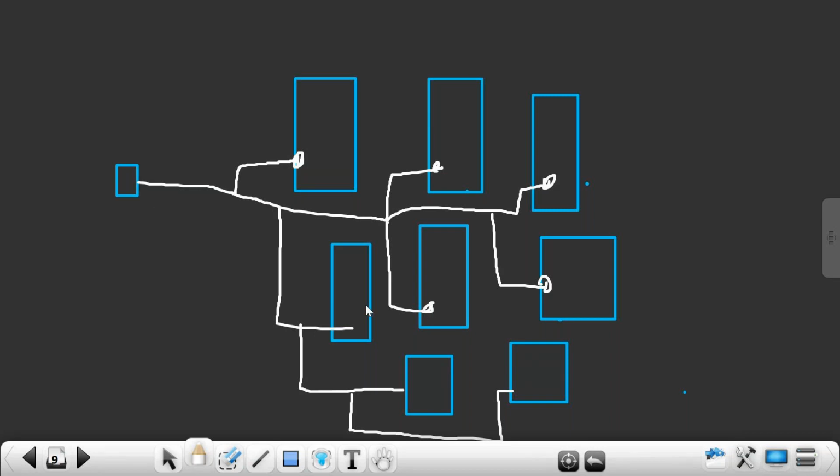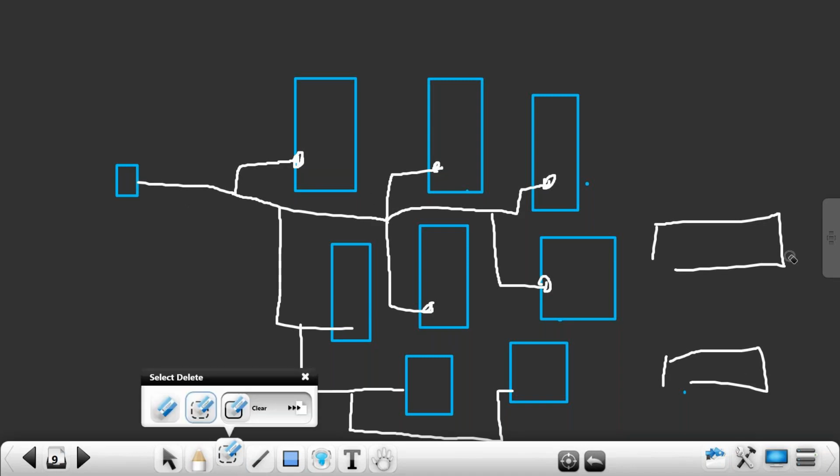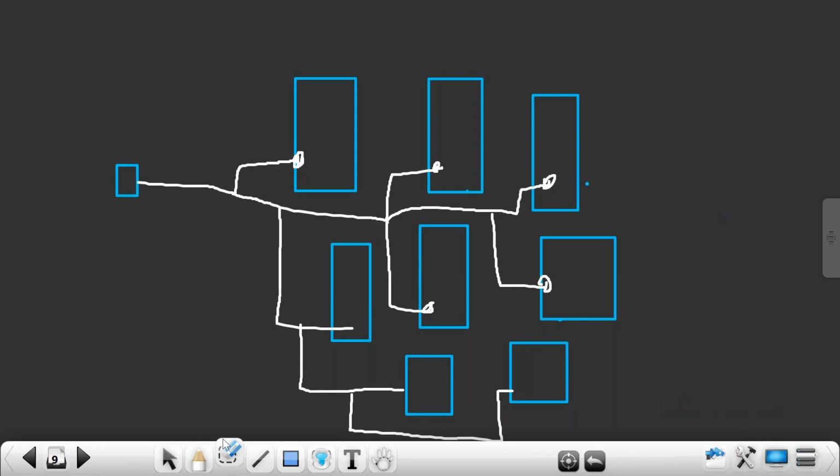The net means a metal layer, which internally has resistance and capacitance, including capacitance to ground. The metal layer acts as the top plate and the ground acts as the bottom plate, with air or vacuum in between. It acts like a parallel plate capacitor, so between the metal layer and ground there is a small capacitance.